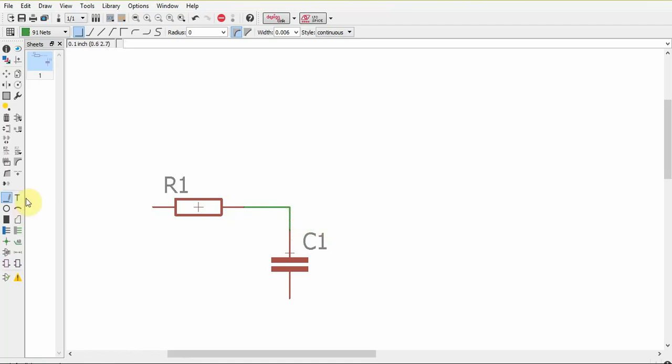So now we'll do wire again and then do this. You might think it's connected, but you can't be sure unless you do this junction. You have to do this manually. Then you know that these two points are connected. Anyway, that was just to explain the difference. So we'll just do a net connection, so we have it all clean and consistent.